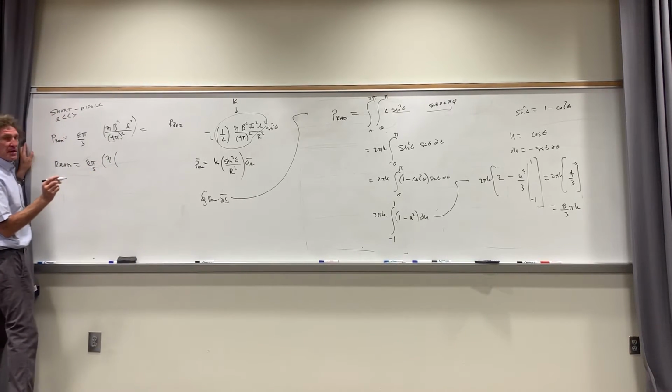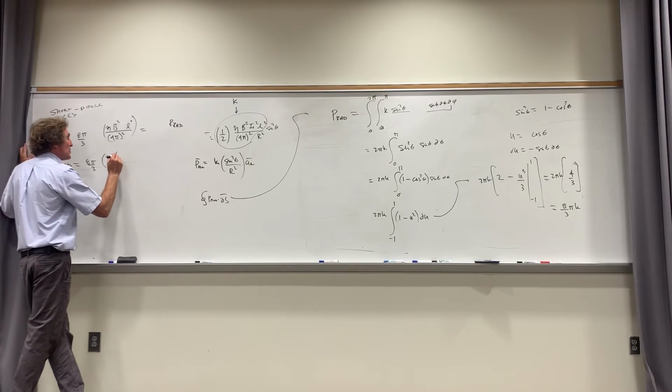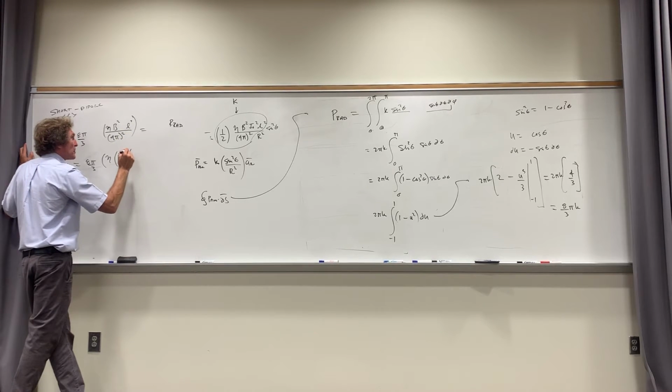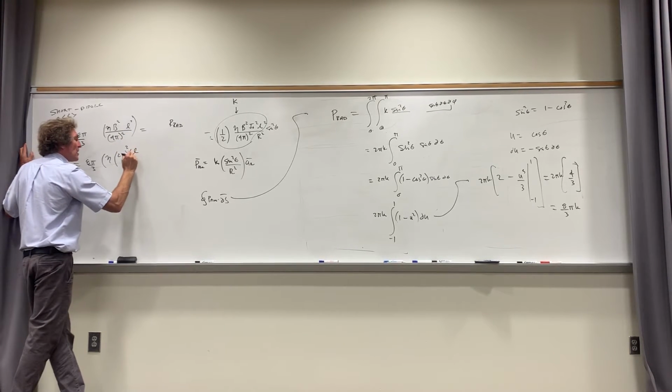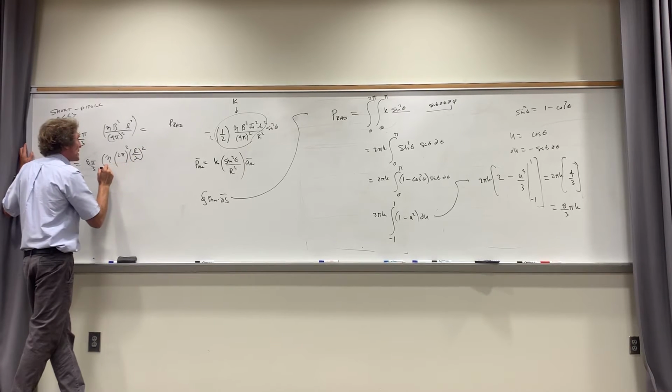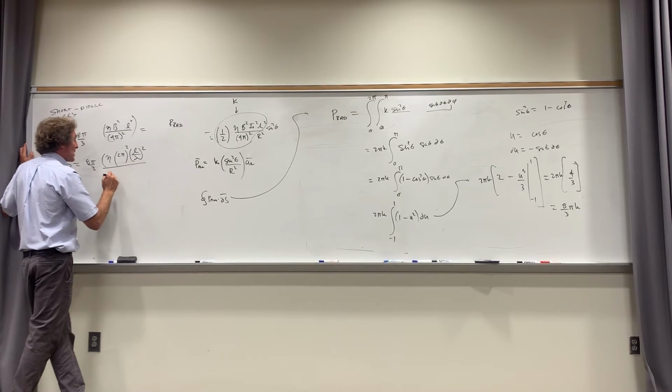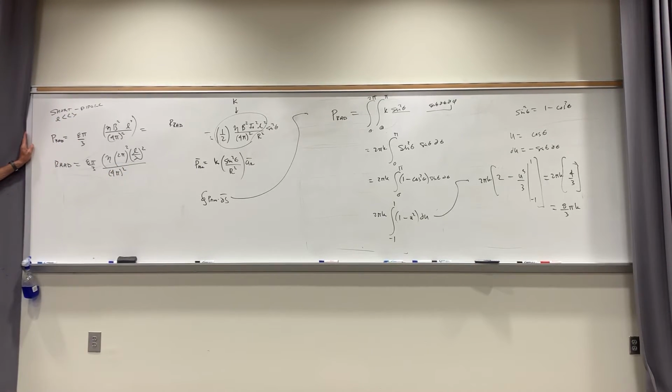Now, beta is usually given as 2 pi over lambda. Remember that, 2 pi over lambda. But instead of putting the lambda there, they put it with L. And they put 2 pi squared, and then they put L over lambda squared. Then they put downstairs 4 pi squared. Are you with me? I'm just trying to clean it up. But they usually have L over lambda because the antenna length that you're talking about is in fractions of a lambda. So that would be like 1/10, 0.1, 0.01, if it was 100th. Following? Now we cancel some stuff next.